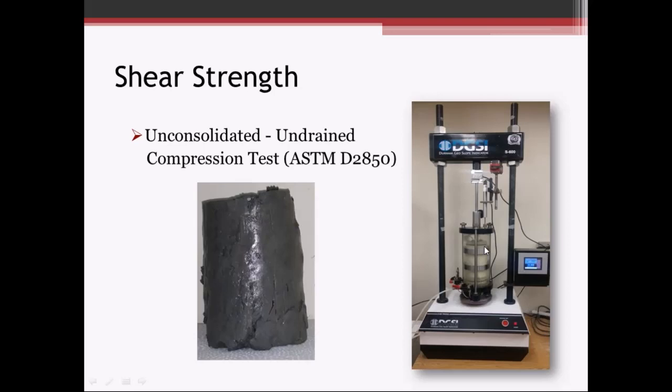And this test can be performed on a Shelby tube or again remolded. But in any event, the engineer needs to specify the remold criteria as well as the confining pressure to run the test at.